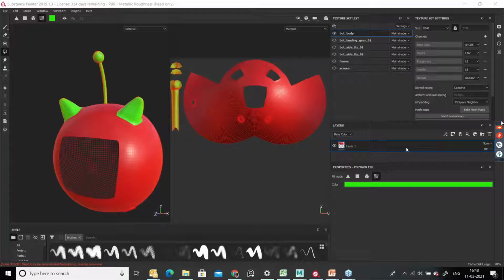Great. We'll go to Ravi Sharma's question. Is it necessary to unwrap the model in Maya before bringing it into Substance Painter? Yes, Ravi. Without unwrapping, how can you apply texture? The texture won't stick on our geometry, and even when you apply strokes, it won't apply to the surface in a proper manner.